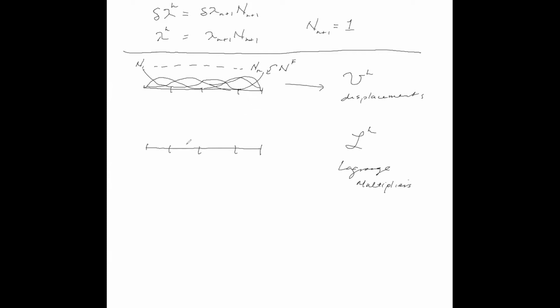But in this case, we have our bar in here, right? And we're enforcing that u at 0 is equal to u naught with a Lagrange multiplier. But since it's just at a point, the Lagrange multiplier is just a number. We're just going to solve for the value of the force. So because that's just a constant, the only basis function I need is a single basis function that's equal to a constant. Yeah, so thank you. That's what we're doing.